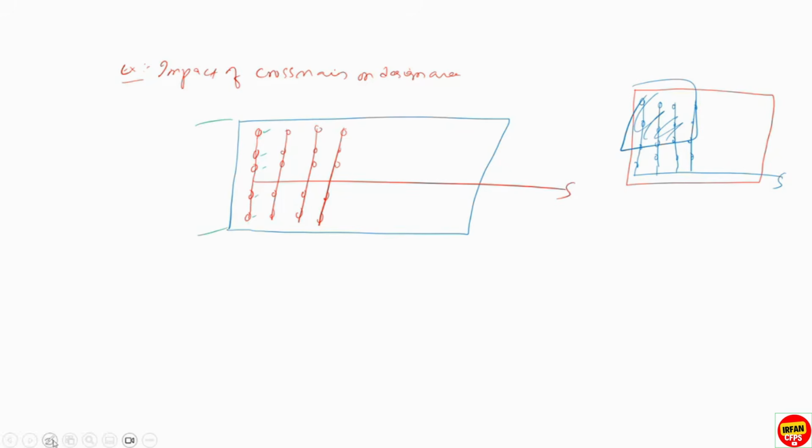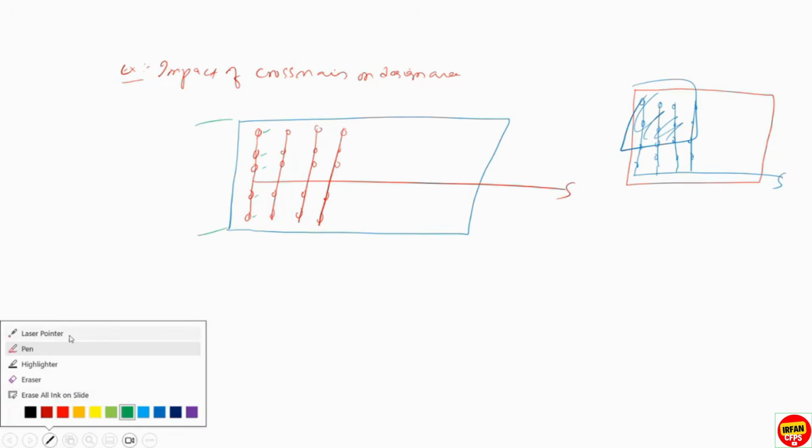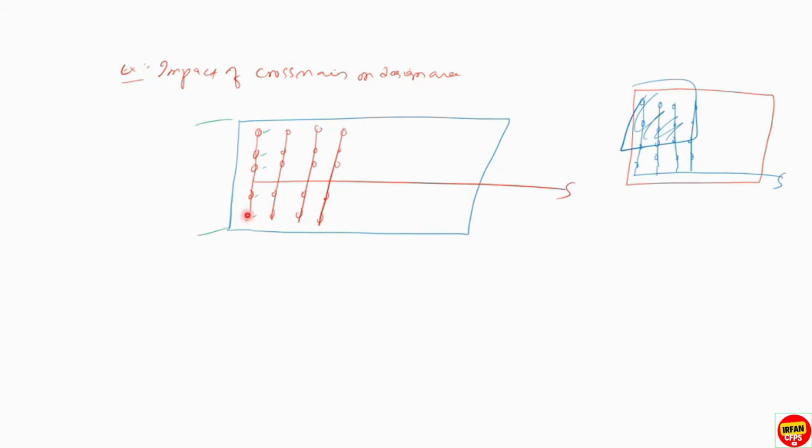So that's why most of the people, the designers or the contractors, select all these sprinklers for the calculations. That is not correct, because if you come from this pump, the remotest sprinkler will be this one. Assume that this is the remotest sprinkler.